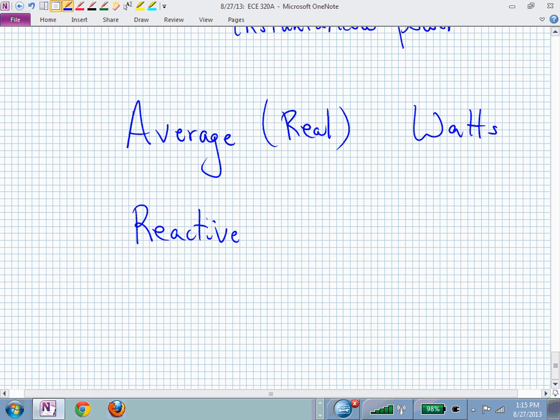In general, power was volts times current. Well, volts has units of volts, and current has units of amps. So we will call this volt amperes reactive, or VARs. So our reactive power will have units of VARs. And if I say, what's the reactive power in that load? You'll be able to find it, and you'll label it and say, oh, that's VARs. Or maybe it's kilovars.